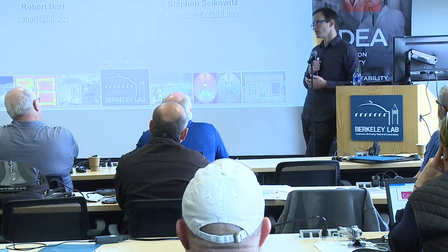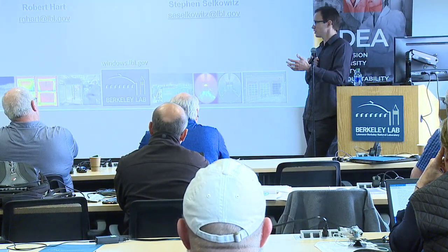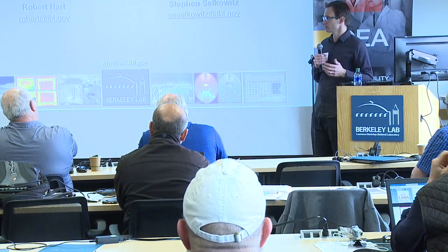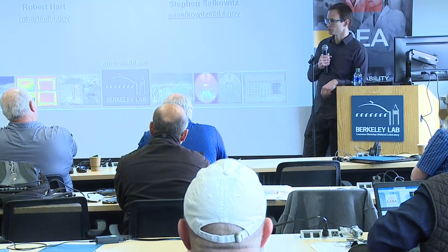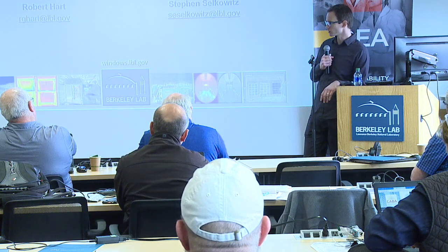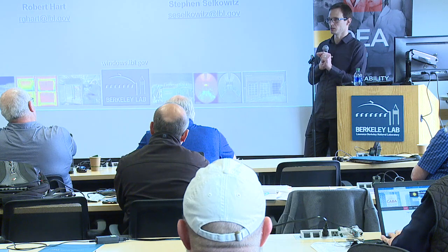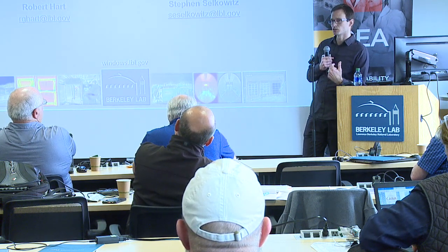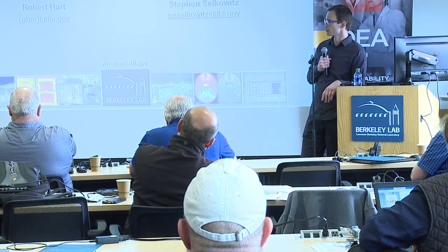There's vacuum insulated glazing, which I think is the most viable future technology that's out there. By that, I mean it exists and it has for a long time. Manufacturers make it. You could go out and buy vacuum insulated glazing today, which gives you slightly better than triple pane performance. And if you make a hybrid, like a double pane window with one of the lights being vacuum, it's a little bit better than quadruple pane performance. But it's extremely expensive. The manufacturing processes are very expensive right now.